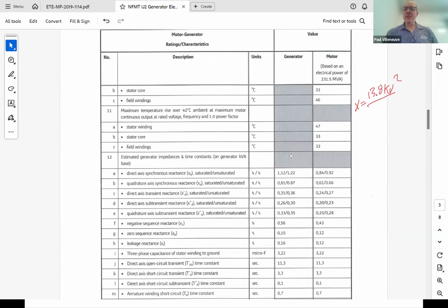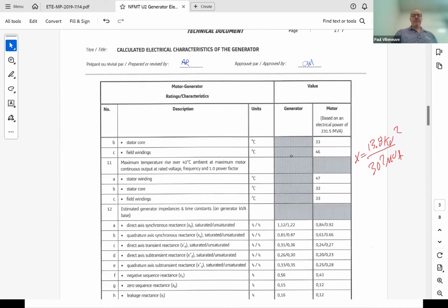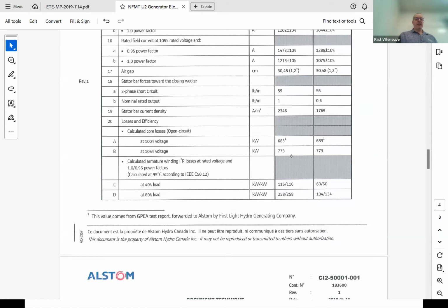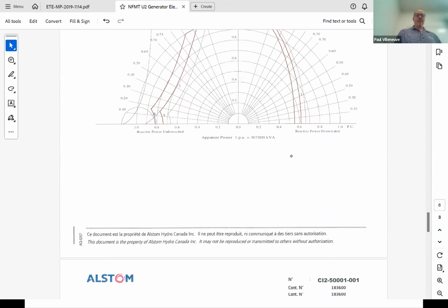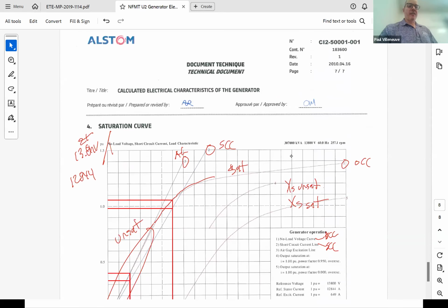Sorry. So if you divide that by, or multiply those two numbers, you should be able to get a comparison. Don't forget, this is a Y-connected generator. So you need to be able to divide phase voltage by phase current to get the right values. So if you're going to multiply by 13.8, that's okay. But don't forget, at some point, you're going to have to divide that by the square root of 3.